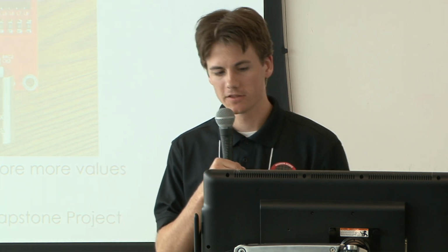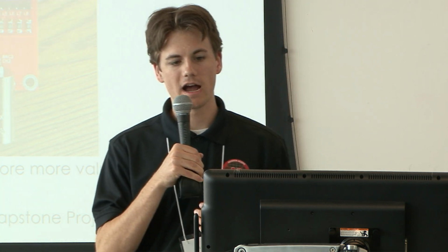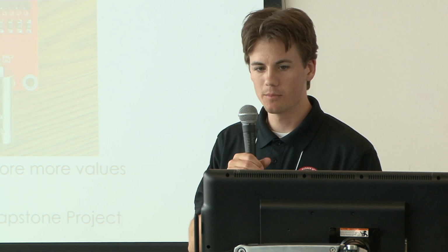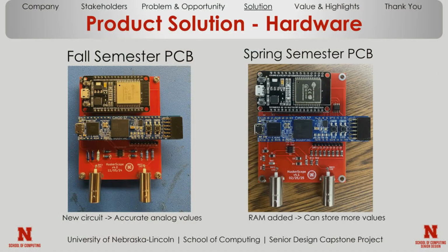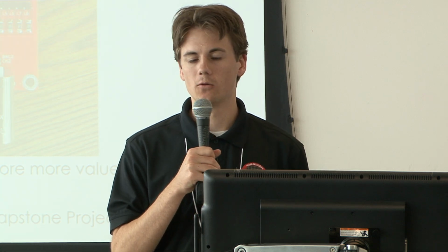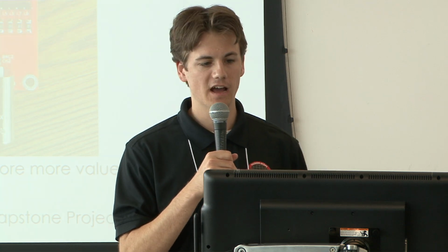What we improved on for the spring semester was we also added a RAM chip up in the right-hand corner. This was to give us more samples in the buffer, so that we didn't need to rely on only using the BRAM on the FPGA.